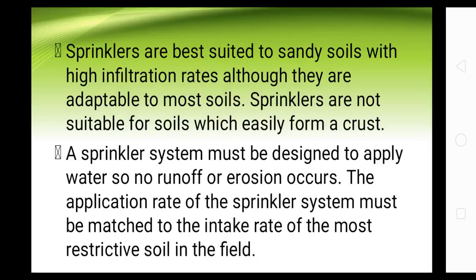Sprinklers are best suited to sandy soils with high infiltration rates, although they are adaptable to most soils. Sprinklers are not suitable for soils which easily form a crust.